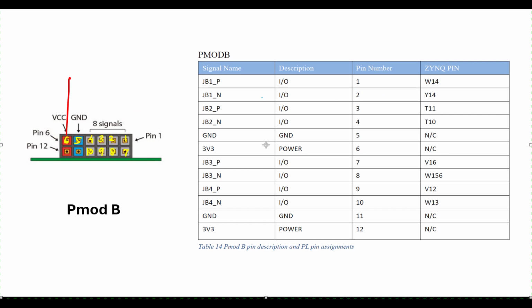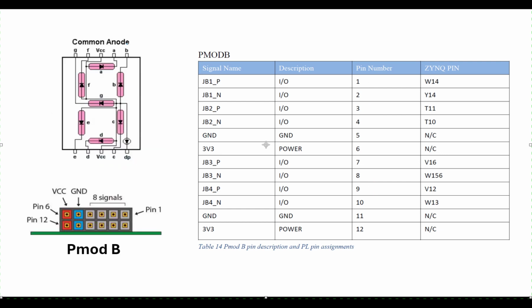For the rest of the things, on pin number 1, I'm giving A, B, C, D, and 5 and 6 not giving anything, F and G, right? So it is these pins 1, 2, 3, 4 and 7, 8, 9 to which I will be connecting my 7 segment display, right?